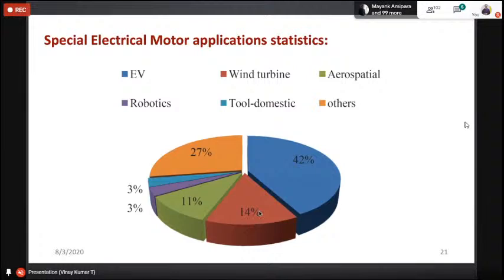If you take permanent magnets on the rotor pole, by using wind you can get mechanical force, right? You don't need to supply any reactive power to the wind drives if you take a permanent magnet synchronous machine. That's why nowadays most of the slip ring induction drives are replaced with permanent magnet synchronous motor drives, special machines.